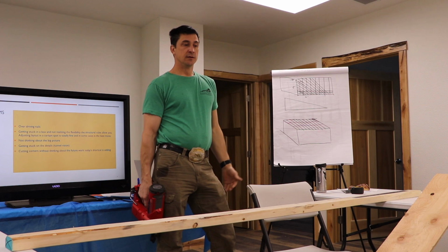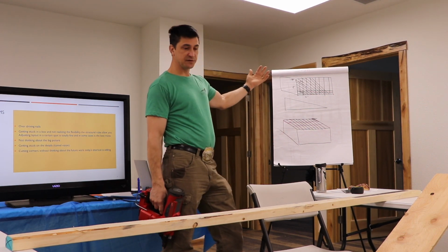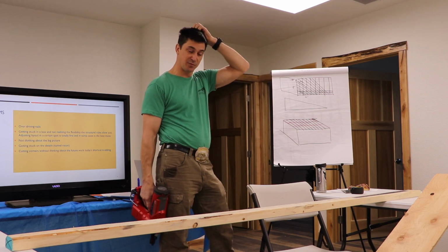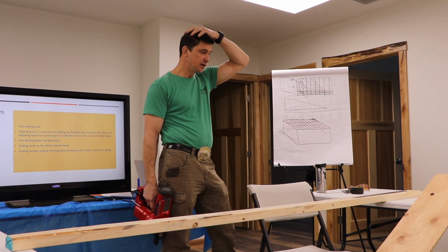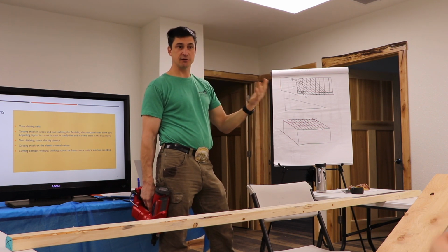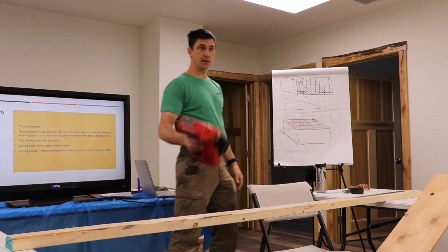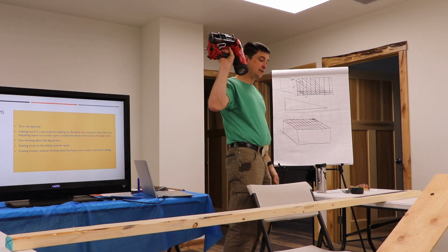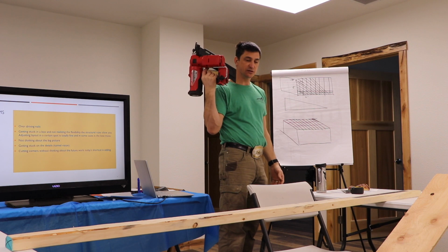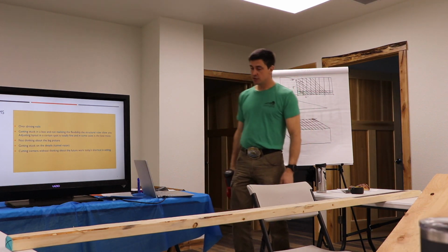Or 3 weeks after you did the sheathing, you got to pull something off, and you go there with your cat's paw, and you're like, doggone it, who was the idiot that overdrove these nails, because now you can't grab any of the heads with your cat's paw. Okay? So little details, like super easy things, can make a huge mess later.